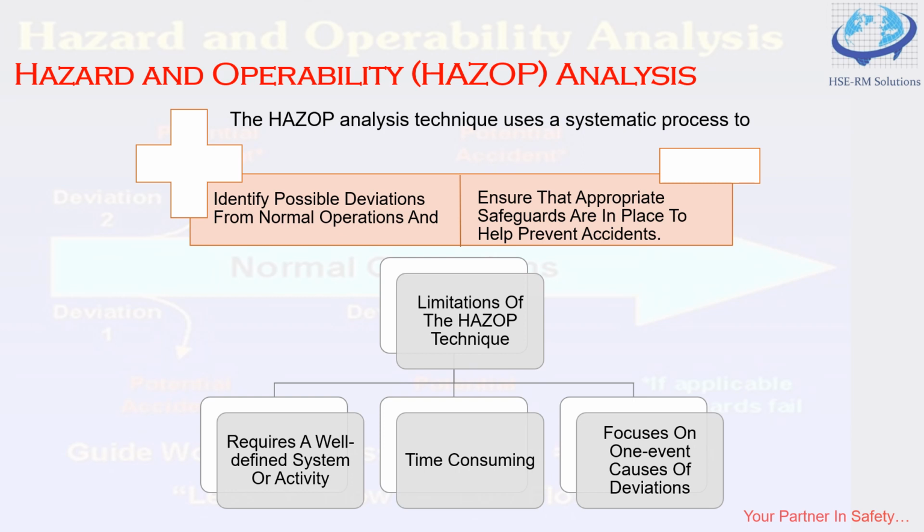The HAZOP technique uses keywords or guide words used by a technical team comprising a system domain or process expert. Now these keywords primarily talk about, first, flow of any material intake, that is, if any material is fed, is it fed or not, what will happen if it's more, less, or it's not fed at all. Now these parameters are site condition and system specific.